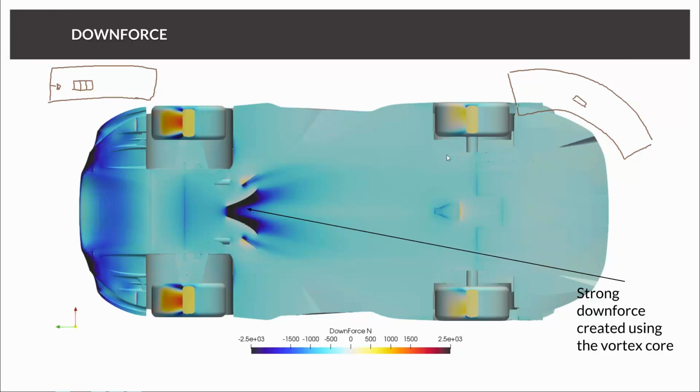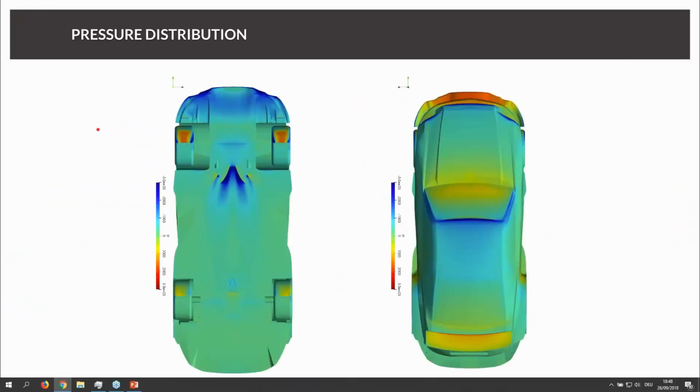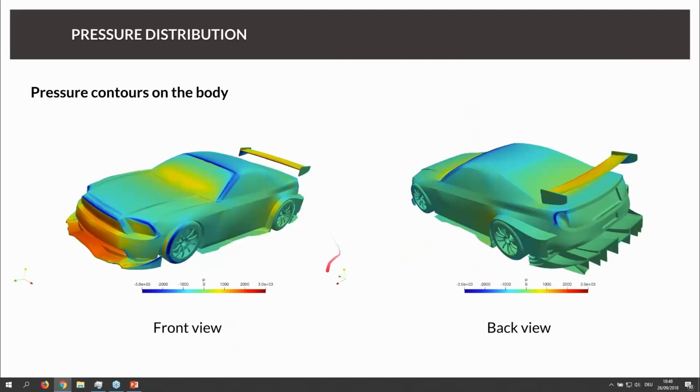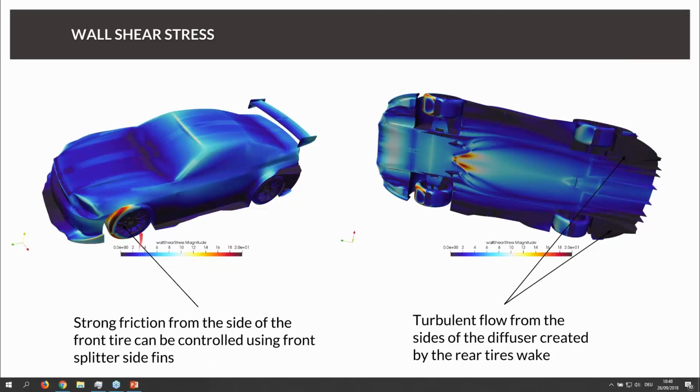Exactly, and Adam gave the exactly right answer to my question. Flow separation happens where wall shear stress is 0, or where the pressure gradient is changing its sign. And Bavin also gets the same question. You are really good, guys. And that's exactly the point. If you want to visualize flow separation, you have two possibilities. One is to, let me erase my drawing first, take a look where the wall shear stress is higher than 0.